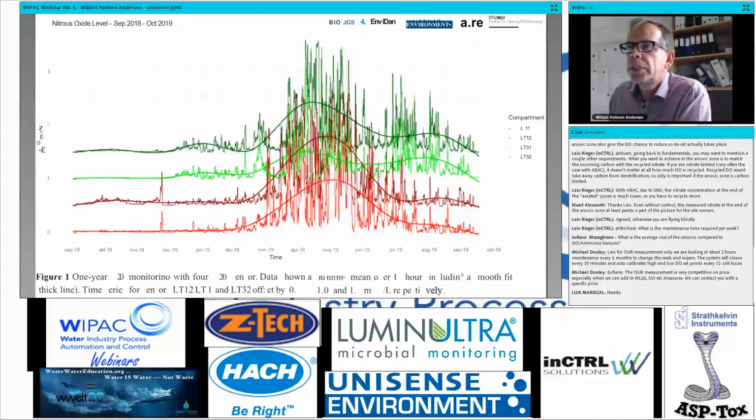We do see during the wintertime at plants where we are efficiently harvesting a lot of COD out for biogas, that we will have problems with efficient denitrification, and that's because the endogenous hydrolysis of COD is very slow when the water gets colder. But the take home here is that you need to measure throughout the year to really understand how to do the process controls. You cannot measure for 14 days or even make a model of this and then get it to understand. The nitrous oxide models are really, really difficult to calibrate and rarely hold their calibration for long.